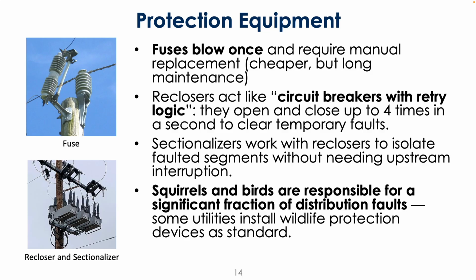As opposed to here, where the recloser opens and stops the current from blowing that transformer. Now the utility doesn't need to come out and replace that equipment, which is a lot more expensive and could have a long lead time. And so that blackout could be many hours, many days, for the utility to come out and replace it.